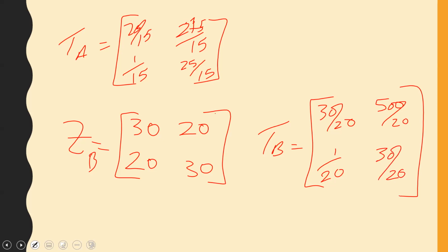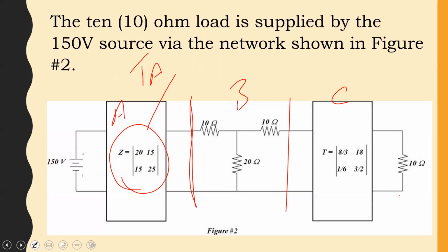I went rather quickly on this for a particular reason, because one, you need to use the theory that you're familiar with. So quickly, you know about symmetry. Because it is symmetrical, if you're looking at impedance parameters, you only need to calculate 2 of them. You won't need to calculate all 4. If you know any 2, you will know the other 2.